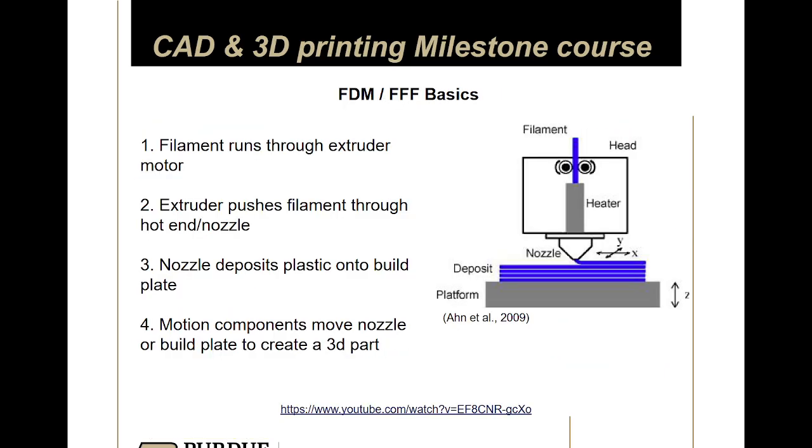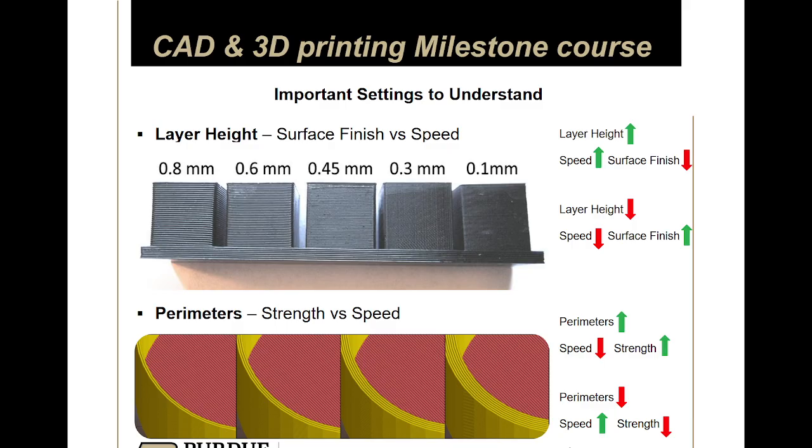Again, like I was saying, it's like 2.5D, so it'll stack profiles on top of each other, and you can change the thickness by changing the layer height. So increasing that layer height will be a lot faster just because there's fewer layers to produce. But that might reduce the resolution, especially in the vertical direction.